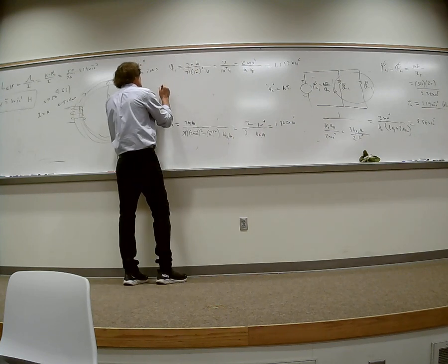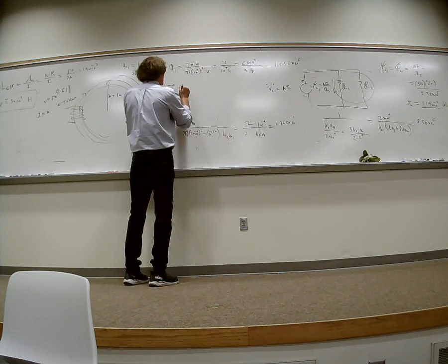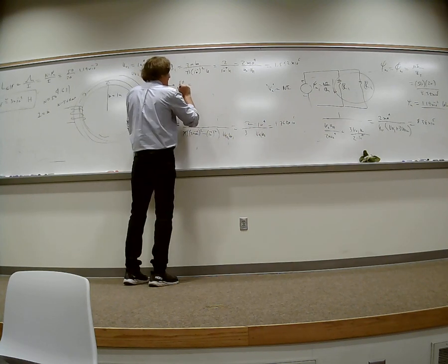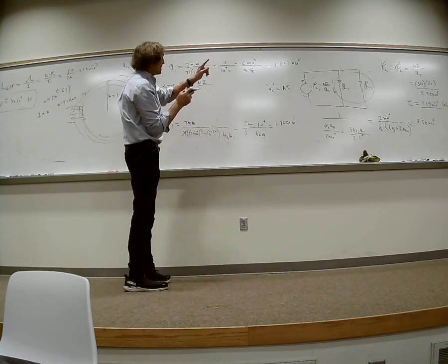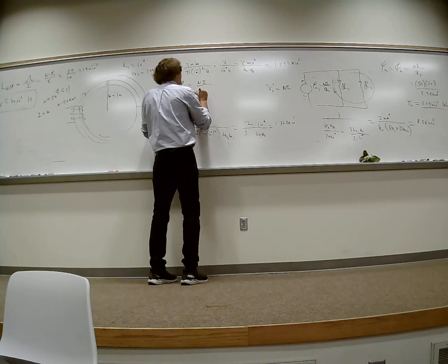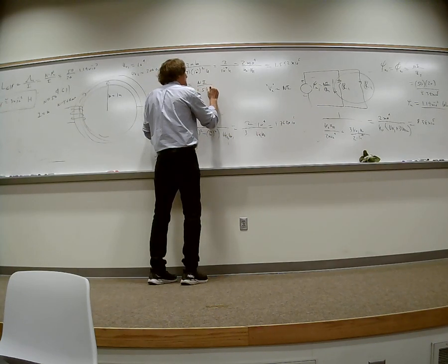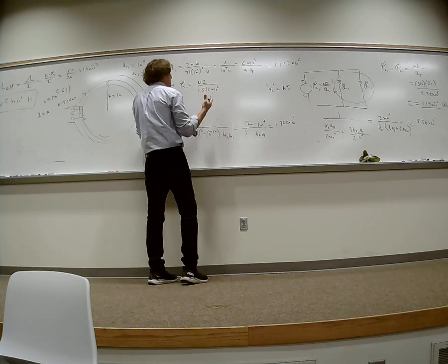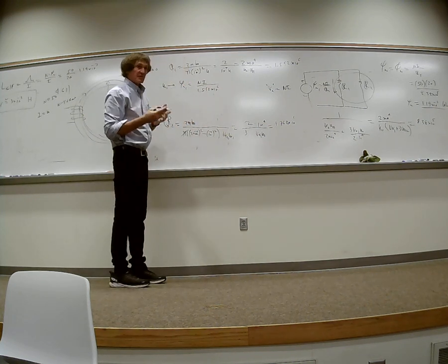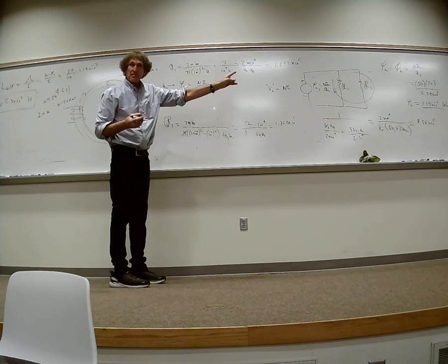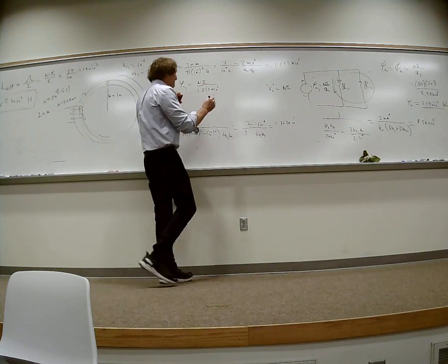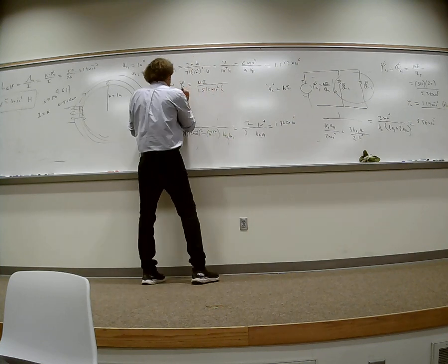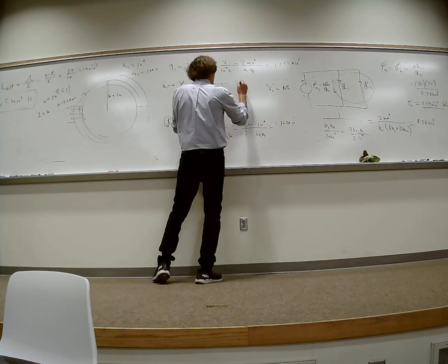So first, this has to do with material 1, or mu relative 1. What is the B field? So first we find the magnetic flux flowing in 1, and that's going to be Ni divided by the reluctance in 1, which is 1.592 times 10 to the 6th. That's the magnetic flux flowing in the first one. You all follow me on that, class? Then I divide by the cross-sectional area of the first one. So then I have to divide this by the cross-sectional area to get the B field 1.